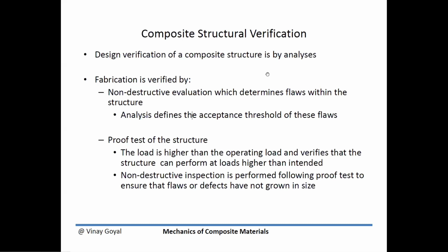So it's very important to understand that every program is going to have unique requirements, but that in general, ingredients such as this could be very beneficial, such as non-destructive evaluation, qualification testing, verifying that you have good workmanship, and then even performing a proof test to check that your structure is robust for the one that you actually manufactured for use in service.